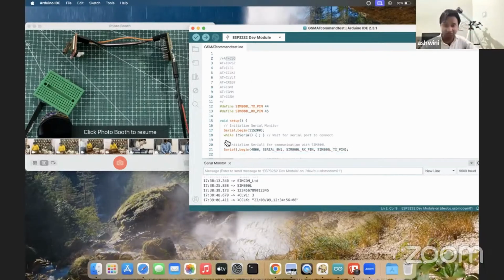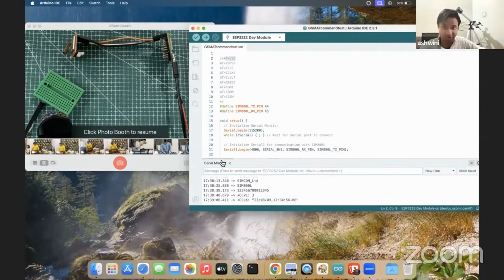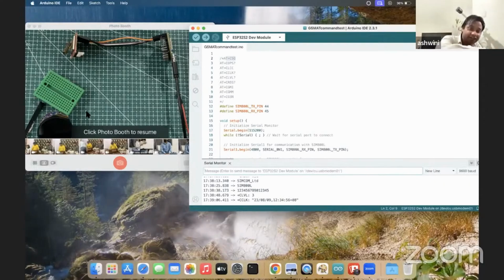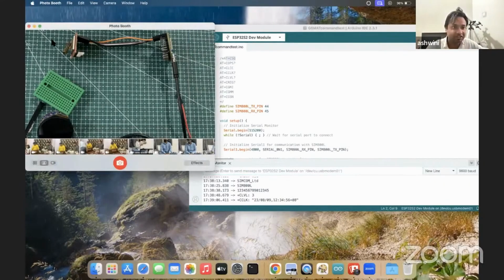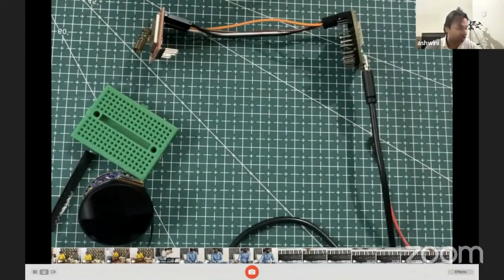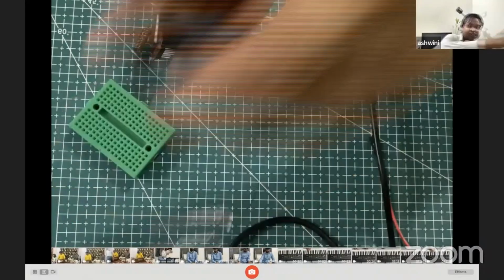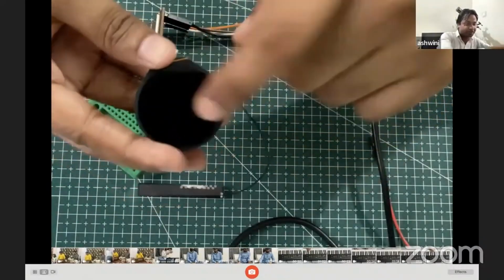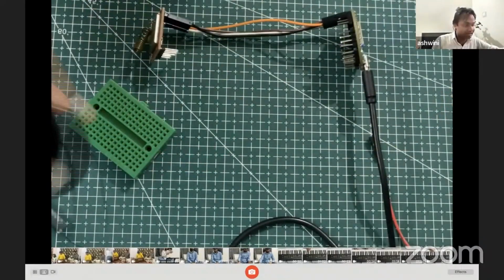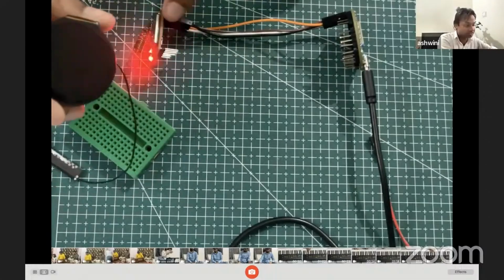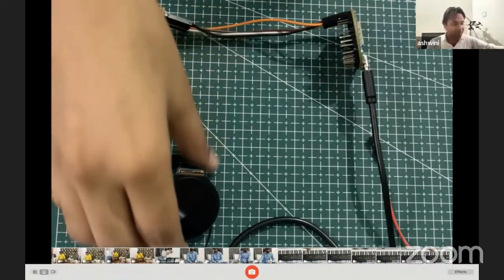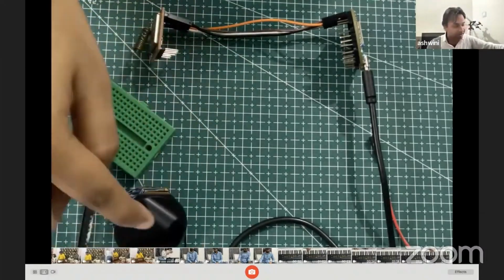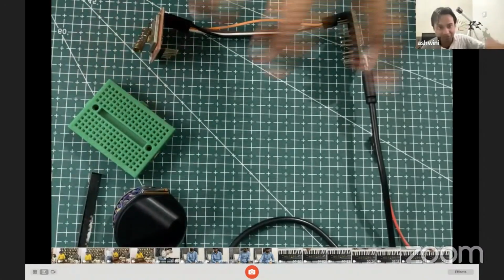Using these AT commands, you can make a call, check the SMS and all other details, and communicate with the module. So this is how we will communicate with the GSM module in the design, and later we will attach this GSM module with this Indus board that has the display behind it, and we will attach this display and this GSM module together. If you want to make a call, we will dial the number, and using the AT command it will transfer and start making the call.